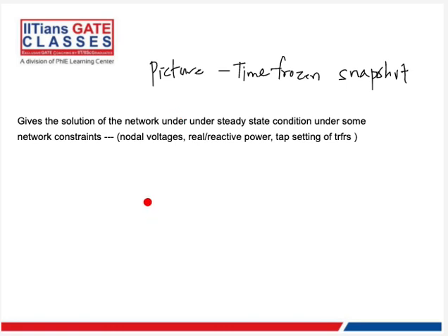So basically, what we are interested in when we're looking at load flow is the parameters: the voltage at every nodal voltage, and the phase angle, right? The active power injection and the reactive power injection, right?